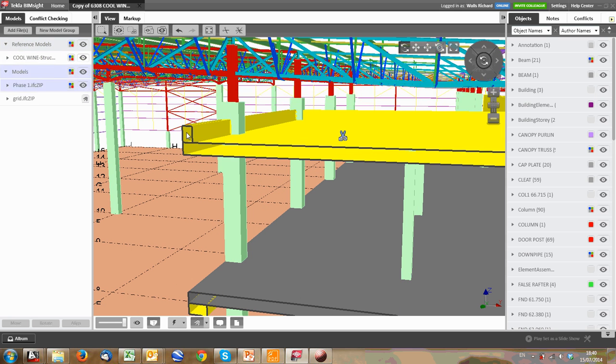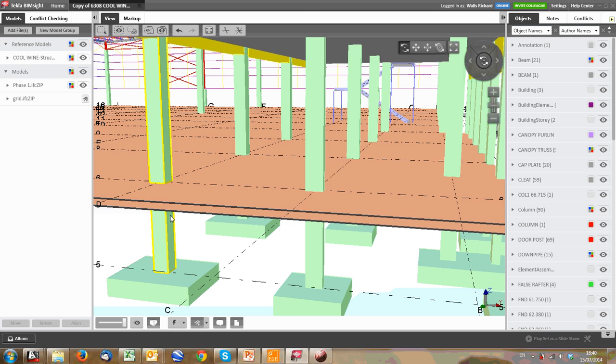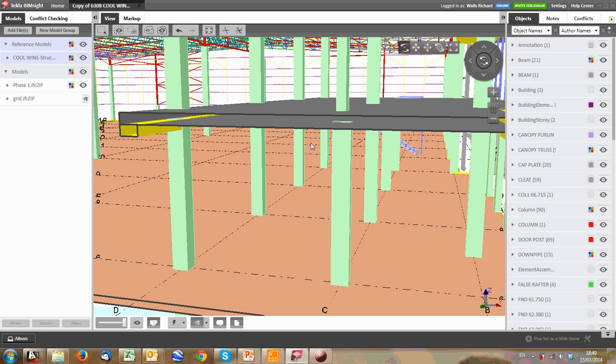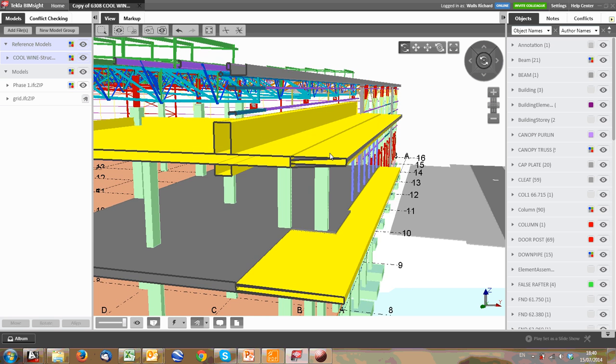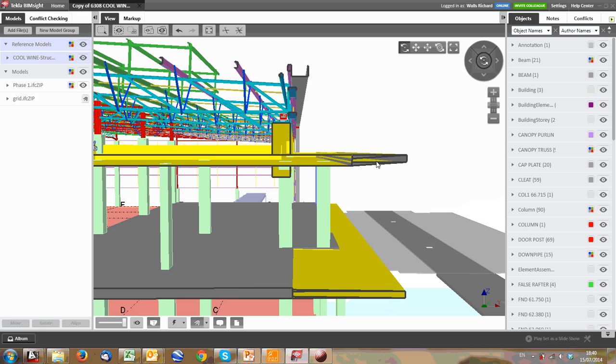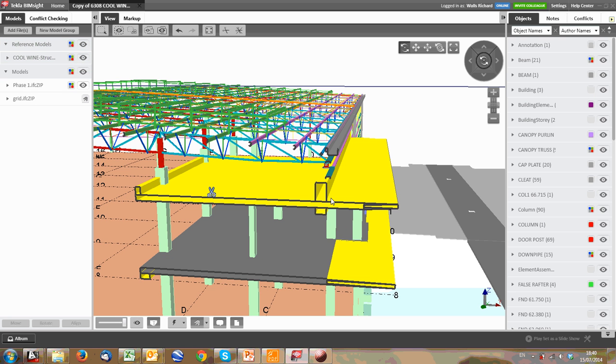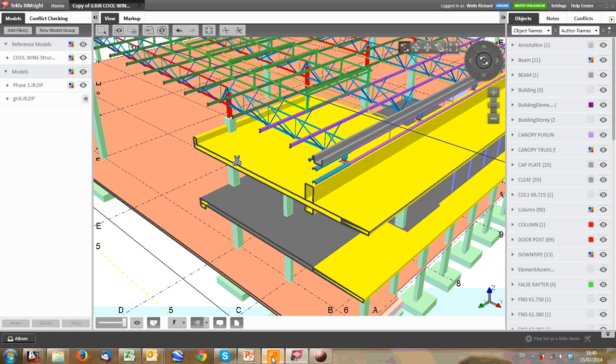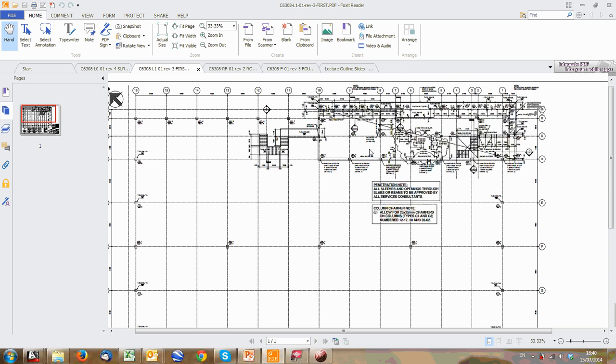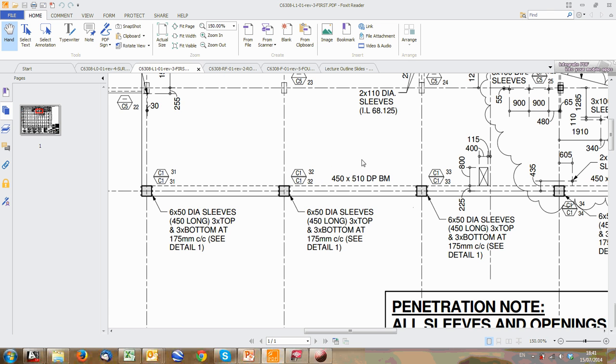You normally demarcate those upstand U/S, downstand D/S, and putting slope. This is a sloped slab in front, but normally you don't get that fancy. So yeah, you go through and start putting all those details on a concrete drawing if you had to. This is what that concrete drawing looks like. So I zoom in, and you can see, there we go, 450 by 510 deep beams.